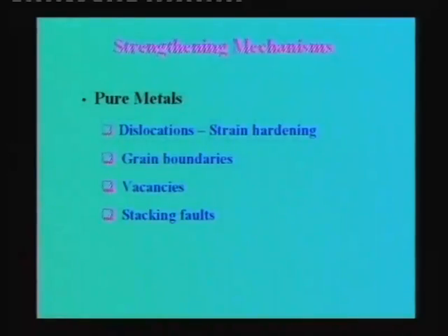But there is another parameter which we talked about when we were talking about the titanium based alloys, which measures to some extent the difficulty for the materials to fail, that is called toughness. This is something which is different from the ductility. One can have high strength and at the same time high toughness. One such example we will see is the grain boundaries. People have shown that one way to achieve high strength and at the same time high toughness is to make the grain size finer.